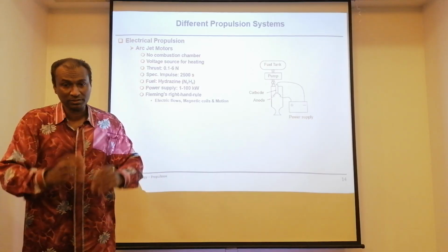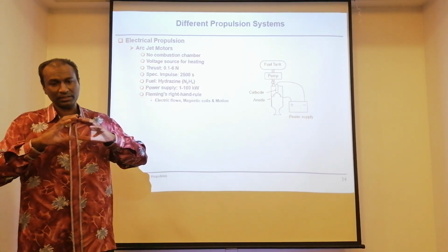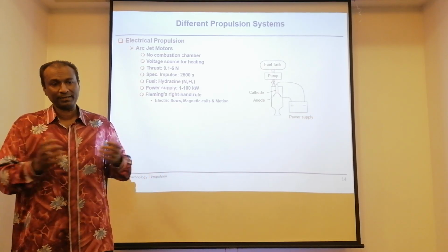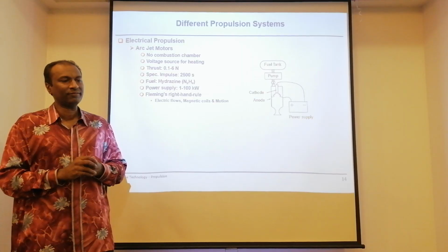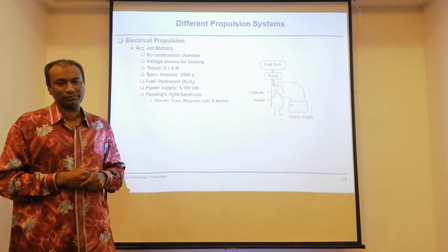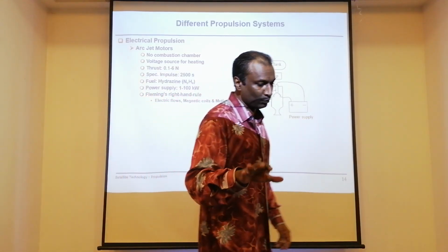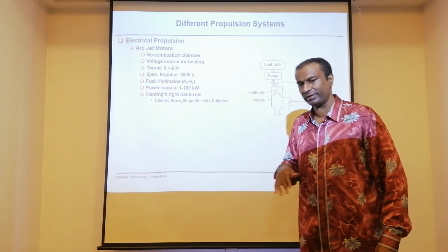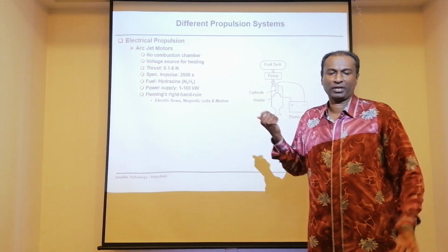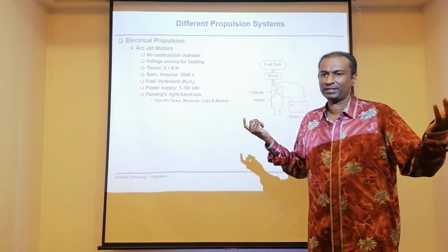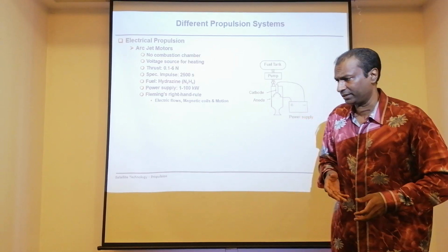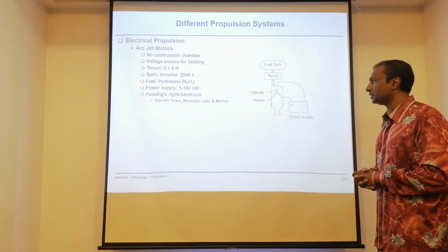So in Earth-bound missions, such as Earth observation, small satellites, FLP, CubeSat, etc., you wouldn't find electrical propulsion or even arc jet motors as an option. If you want to fly an Earth-oriented mission, you may want to look at the bipropellant options. You can typically use hydrazine or monomethyl hydrazine, MMH, with an oxidizer, N2O4, which is nitrogen tetroxide.